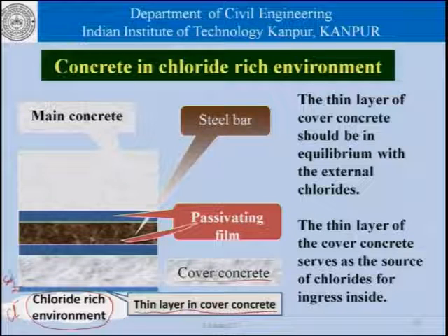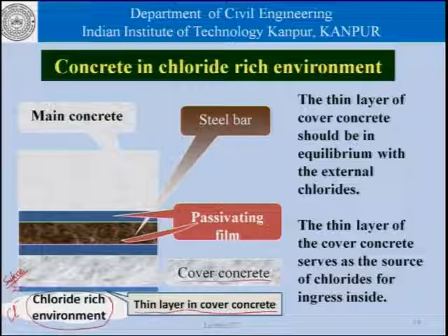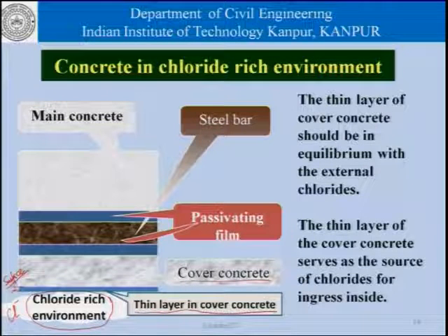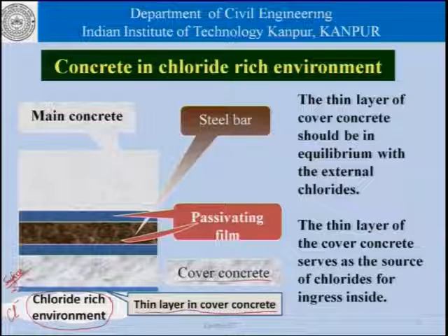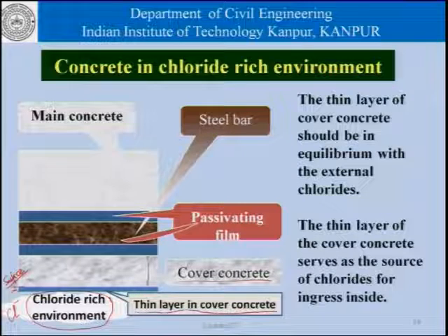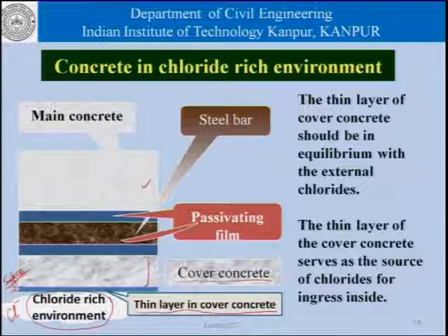The chloride in the environment has to be in equilibrium with the chlorides present in the pore solution in a very small thin layer which is close to the surface. So, we are further dividing the cover concrete into a thin layer of cover concrete which is in contact with the atmosphere, and the normal cover concrete which is somewhere here, and of course, that is different from the main body concrete shown beyond the reinforcing bars, and the passivating film of course is as shown.